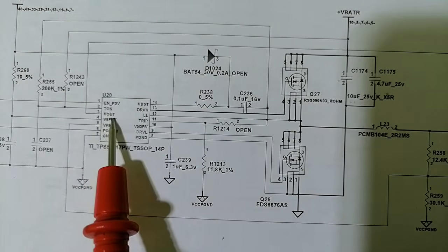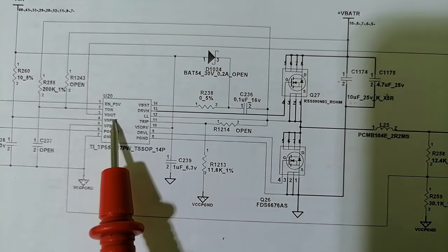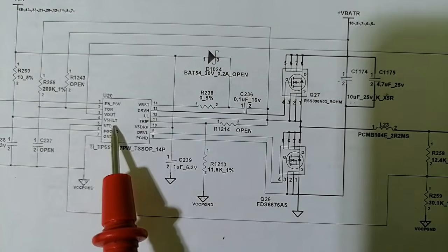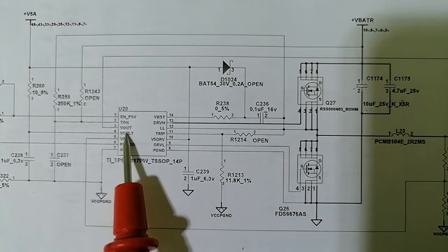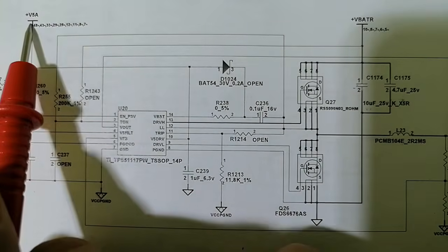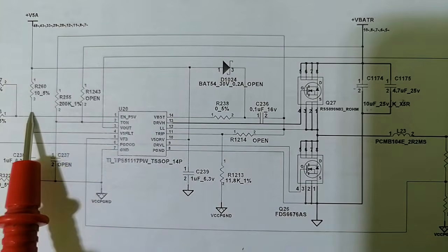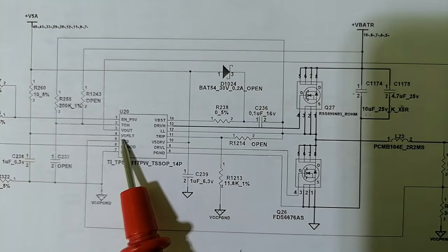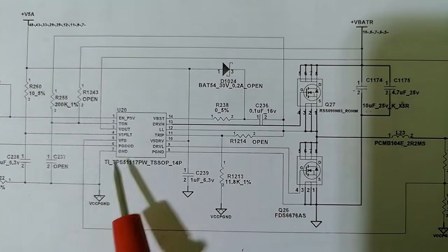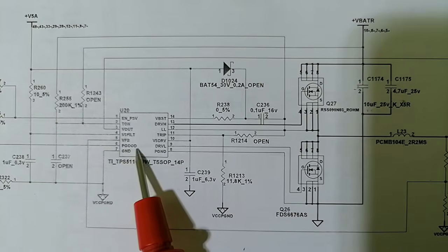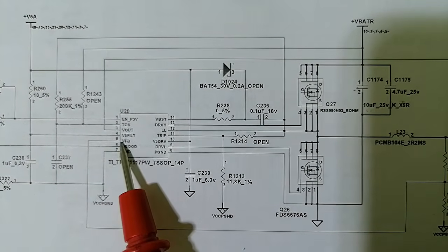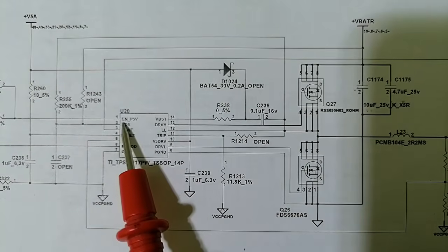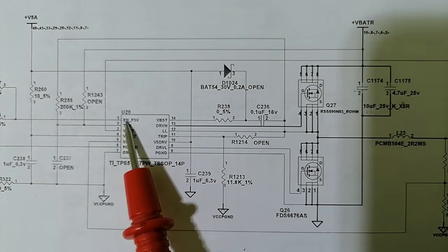But to get this V out here, we need inputs first. Inputs, for example, like the VCC, as you can see here, 5 volt. Do you see here? This 5 volt is the first input. We should get 5 volt here. We should also receive power good. So the IC should receive power good. And also, as you can see here, EN means enable signals.